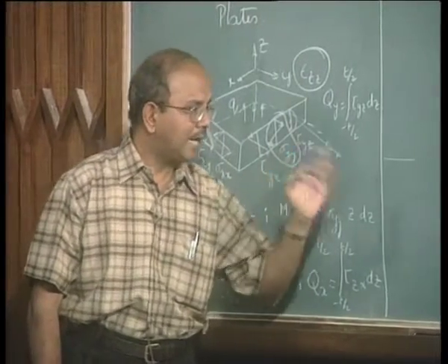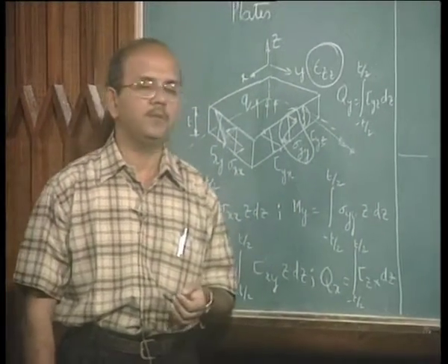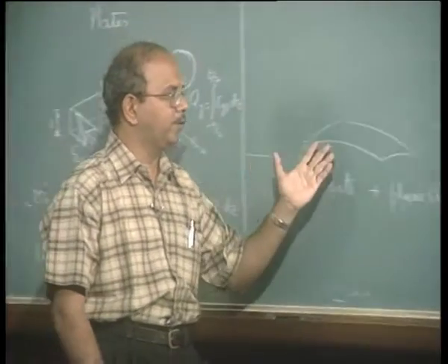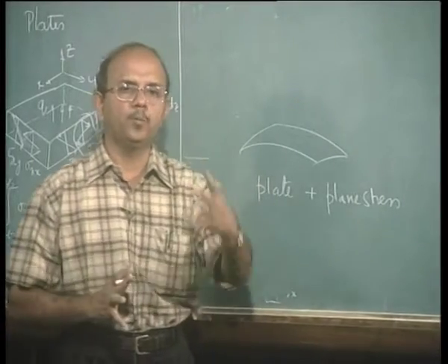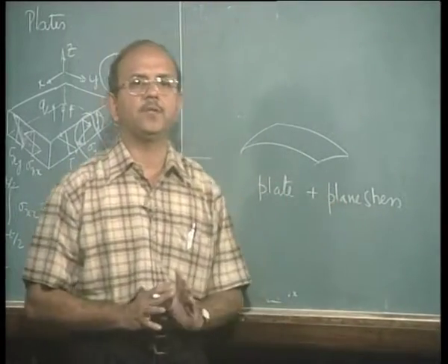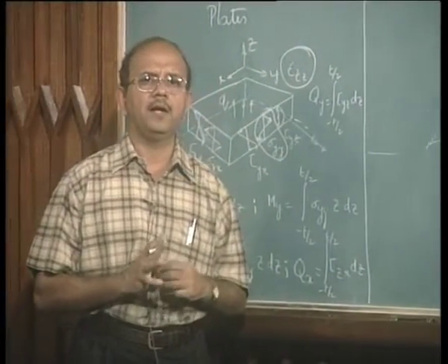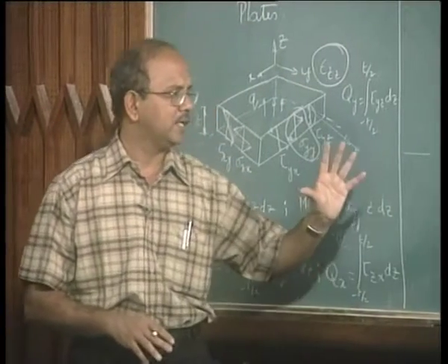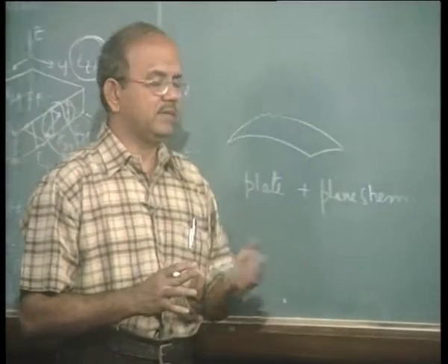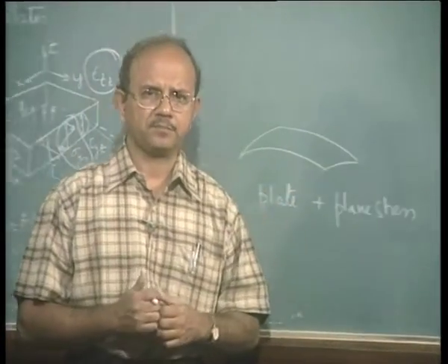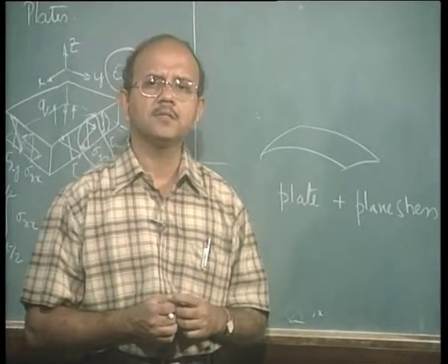Now with that background you can immediately pick up and tell me that look, the formulations are quite simple. We can put the equations in such a fashion that I can superimpose plate and plane stress behavior in order to get shell. Yes, that is a good beginning, and many elements are formulated by some sort of that kind of superimposition, but generally they have some difficulties and they do not perform that well under many circumstances,